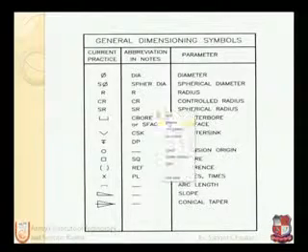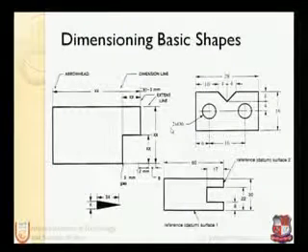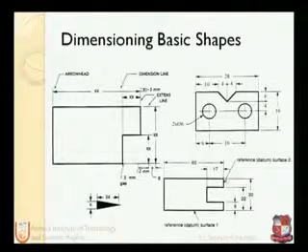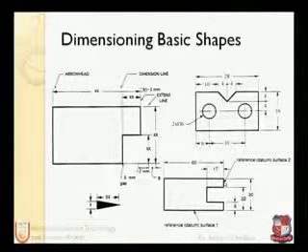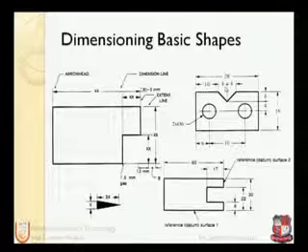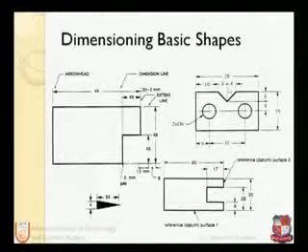And also, for example, in this figure we have 2 holes. So here it's written 2 times 6 diameter, and this edge is the reference datum surface. This is defined as a datum surface. So these dimensions are shown as parallel dimensions, and here we have this dimension as a chain dimension. So we have seen all the types of dimensions here, and it's given from edge to edge.